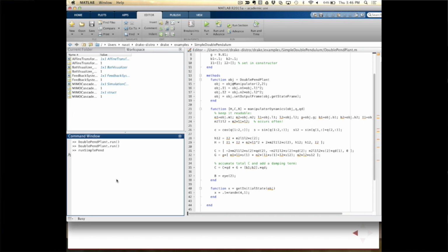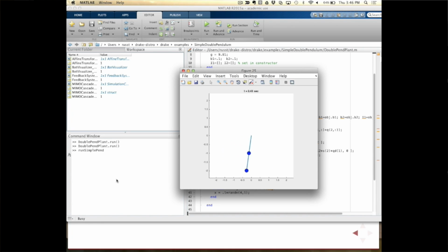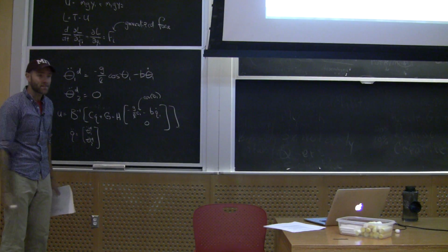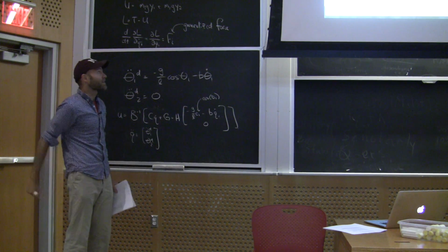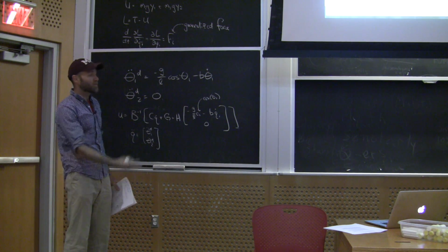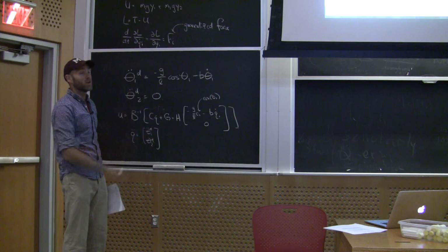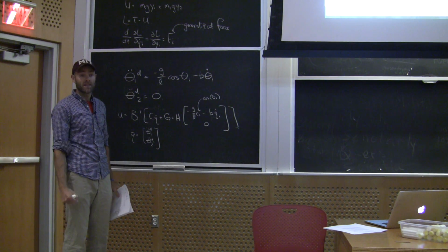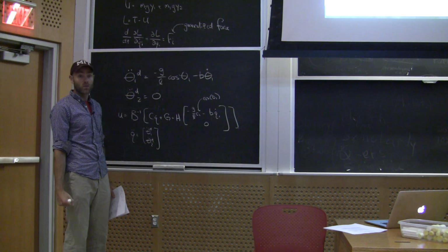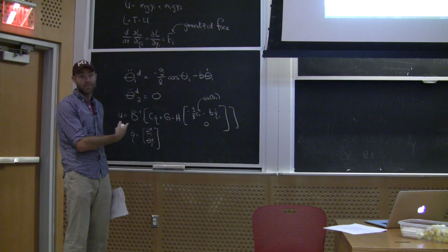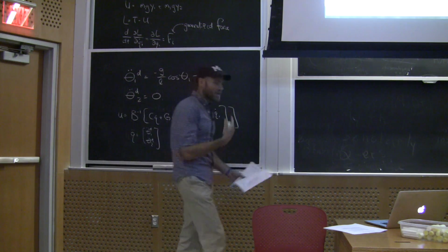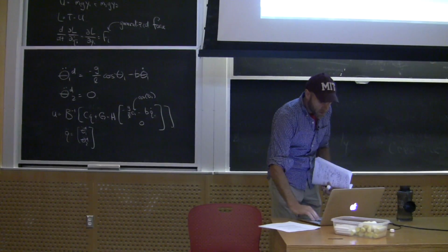Assuming I started with theta double dot equals 0, since I didn't stabilize it here, then it's going to act like I've just replaced the dynamics. I've taken my beautiful second order 2 degree of freedom dynamical robot and turned it into effectively a 1, just using high gain feedback, right? Those motors are potentially doing a lot of work to make that happen, but the math is easy, right? In fact, I could do the same thing if I just flip the sign of gravity, right?